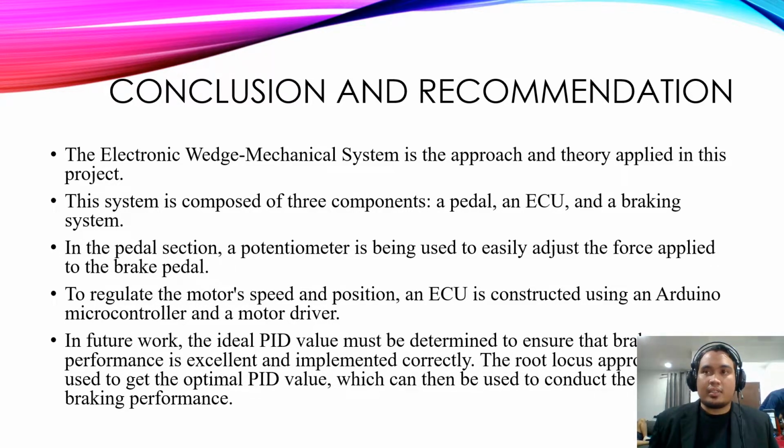Okay, for the conclusion and recommendation, the electronic wedge mechanical system is the approach and theory applied in this project. The system is composed of three components: a pedal, an electronic control unit, and the braking system. In the pedal section, a potentiometer is used to easily adjust the force applied to the brake pedal. To regulate the motor speed and position, an ECU is constructed using an Arduino microcontroller and a motor driver.